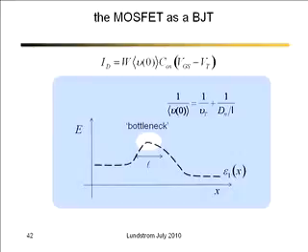And we can always write the current as width times average velocity times charge. Charge is given by MOS electrostatics. Average velocity is just given by those terms on the previous slide. It's the slower of two velocities. D over L physically represents the average velocity that carriers are diffusing at.